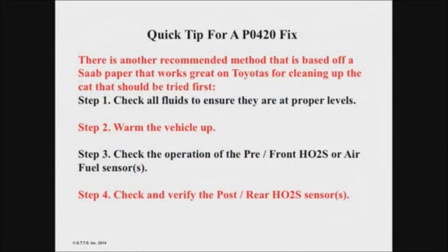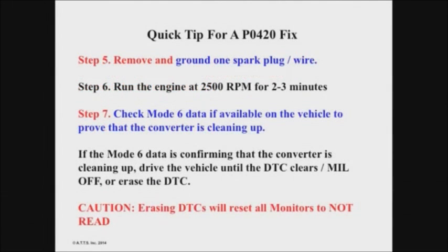Here's another quick tip. This comes off a Saab paper. Saab had something to help clean up their catalytic converters: check the fluids are good, warm the vehicle up, check the front and rear O2, make sure the post O2 is good as well. Remove and ground one spark plug wire. What do you think you're doing? You're loading the cat up big time, right?